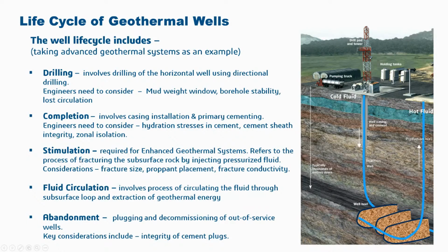The stimulation is a step which is specifically required for enhanced geothermal systems. As I'll explain in later slides, enhanced geothermal systems are systems that require fracking the reservoir. So in these kinds of systems, you need to stimulate the reservoir by creating fractures, using an additional step of fracturing the subsurface rock by injecting pressurized fluid. The typical considerations while performing stimulation of the reservoir rock are the size of the fracture, the trajectory of the fracture, if you're putting proppant, the proppant placement, and the fracture conductivity of the fracture created through the hydraulic process.